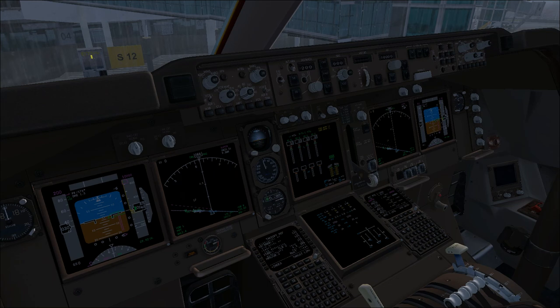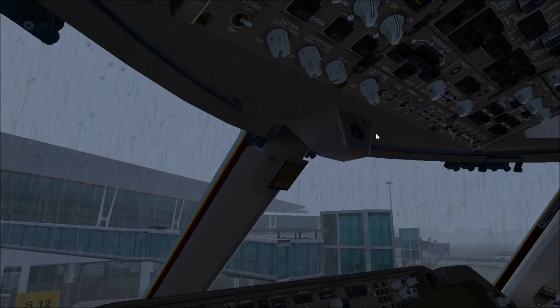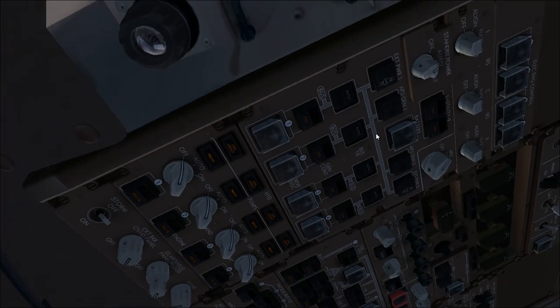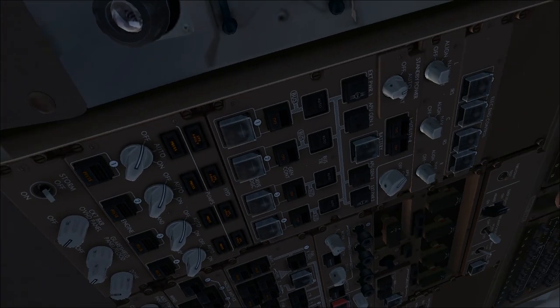And if you go on, we can continue with the pre-flight procedure of the first officer, starting from the overhead panel in the upper left corner. First of all, you have to check the engine auto start, which is on. In this case, in some 747s you have an auto start switch positioned over the electrical engine control. In this case we can just skip this passage. The electrical engine control switch must be in normal position and the alternate lights must be extinguished. We can check it out, all in normal, the amber light is extinguished, so we can continue.